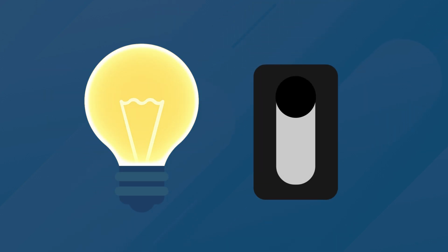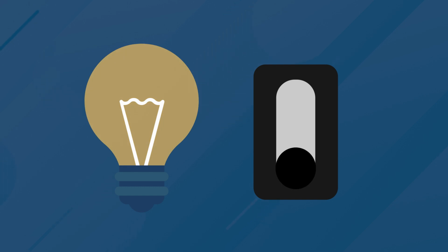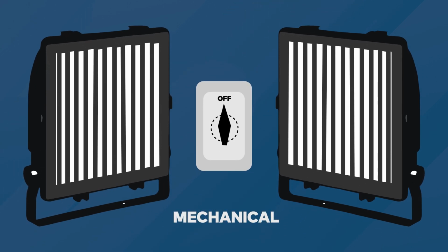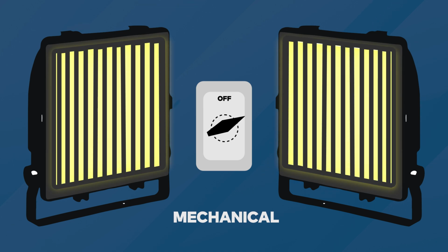The easiest way to control a light is to switch it on and off by applying and disconnecting electrical power. All electrical lights can be controlled this way, but of course, this does not give much variety in lighting output. A creative way to control lights which cannot be dimmed is to use mechanical devices that will intercept or divert the light before it exits the fixture. These can be seen in sporting arenas where the HID floodlights have to be dimmed for artistic purposes.